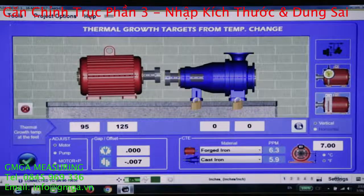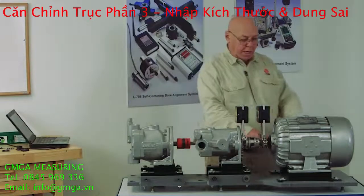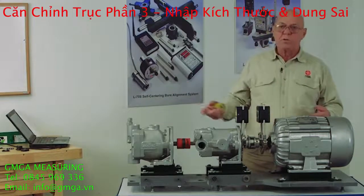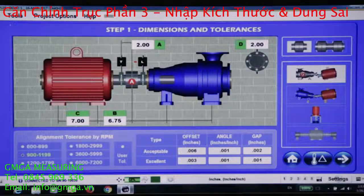I can do the same thing with the pump. I'm going to turn those off. I'm going to set them all back to 0 so we don't have any thermal growth. And then check there. If I wanted to use dial indicators, I could put a dial indicator here and run this from cold to hot and see how much the actual change was. Put those dimensions in there and it would still give me the offsets. Okay, let's move on to taking data.